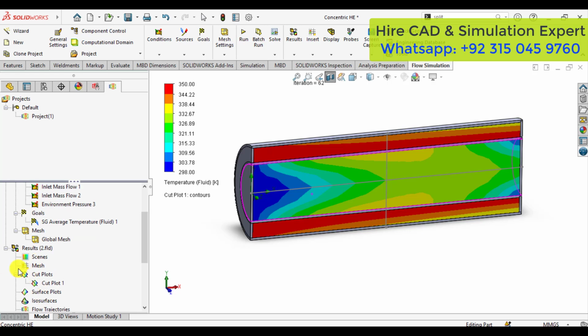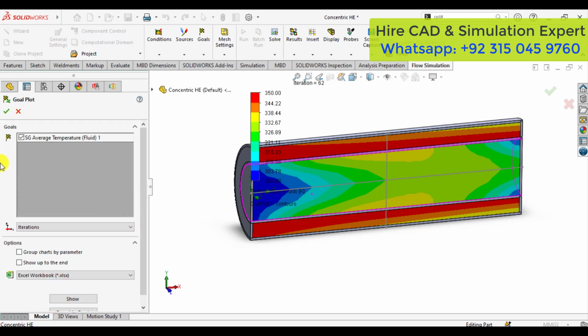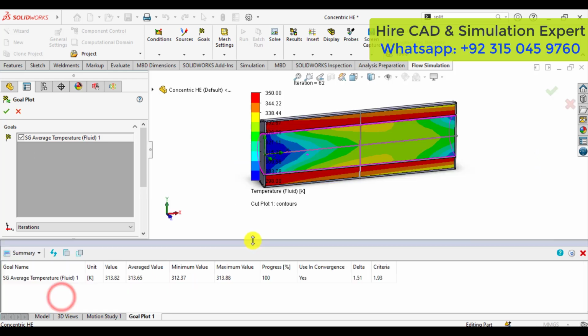Now go to the surface goals. Go to the goal plots. That was the average temperature at the exit of the cold water. Show. You can see the average temperature value is 313 Kelvin. That was at 298 Kelvin in the initial. That has been increased to 313 Kelvin.